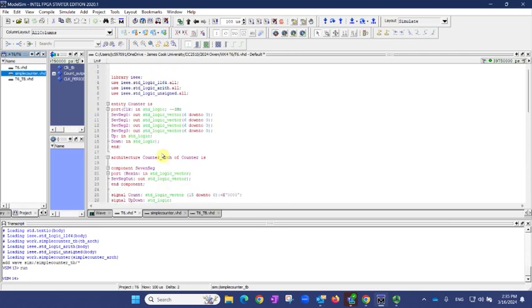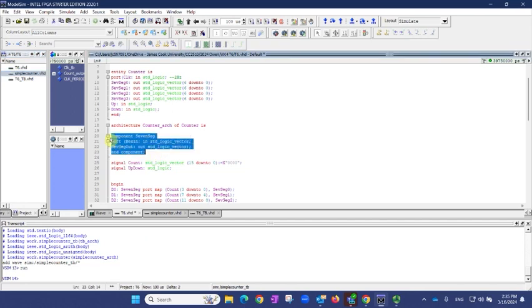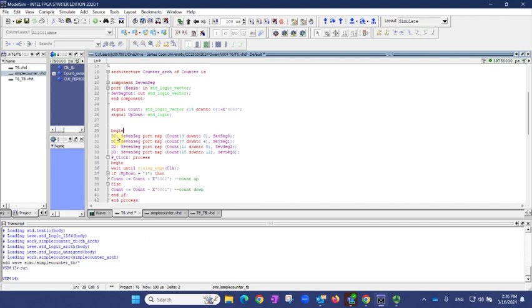So come back here. To call that subsystem, you need to declare the 7 segment first. After you begin the architecture, you can do something called a port mapping. You use the 7 segments, you call this keyword. This is the name of this instantiation, and you say 7 segments, use that. Port map is the keyword, and you put this one as the inputs, this as the outputs.